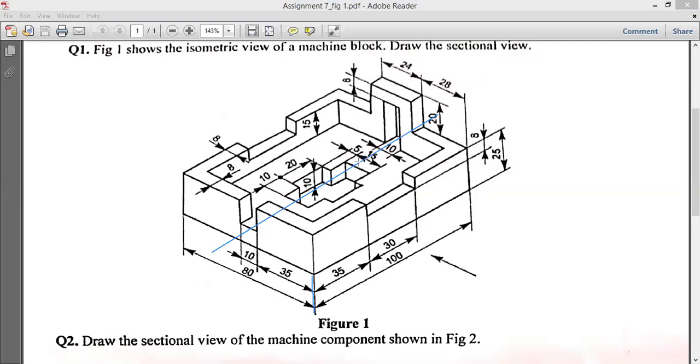So we have to show this section as a sectional view by using the hatch lines. And this is the hollow section. So when we are considering the sectional view, we have to consider the mirror section. That means we need not draw all figures, because this is a similar figure. With respect to this line, this part and this part both are similar.